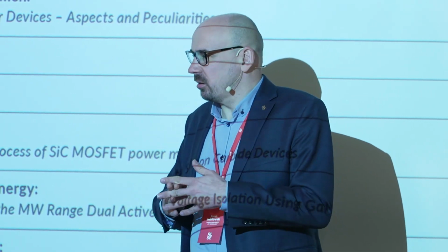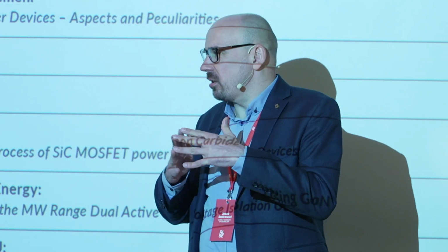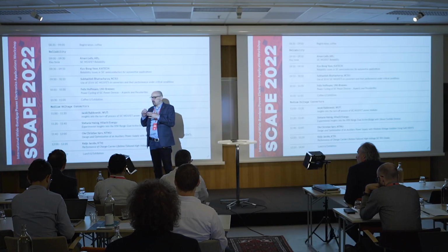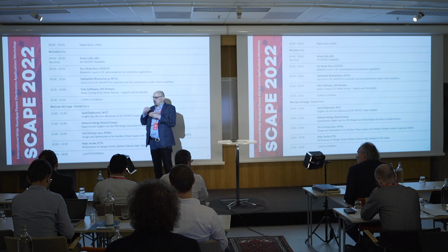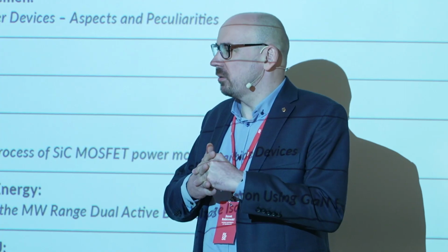Yes, of course. I was not mentioning those details because for the first method, you also have to use the internal gate source voltage, not the external one. And also for the voltage, you need to synchronize it properly with the current, and also you need to remove the voltage drops across the inductances. We did it, of course.